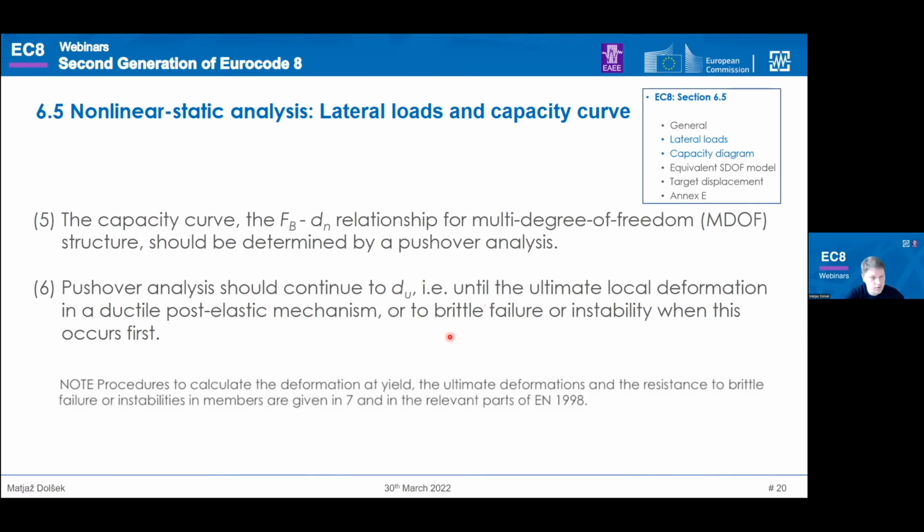Then when you perform the pushover analysis, you can get the relationship between the base shear and the control displacement. As I explained before, the pushover analysis should continue to the ultimate displacement, which is attained at the first member. It can be either a ductile mechanism, or a brittle failure or instability of the structure. Okay, so this is about the procedure of the pushover analysis.